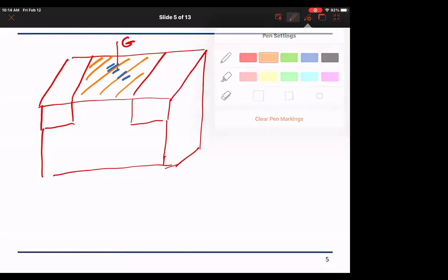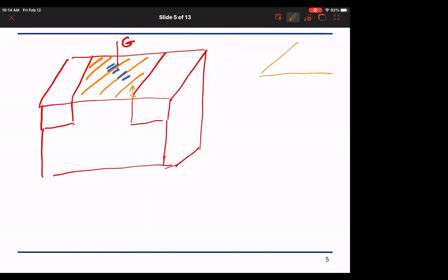The thickness of this oxide layer, we agreed, is Tox. Above this oxide layer, I have the gate, and under it, the channel is residing, right? Because the channel is interfaced to the body, which is grounded. And what happens here is I have a charge accumulation, so the channel will have all the electron charge, and the gate will have all the positive charge coming from the gate voltage.